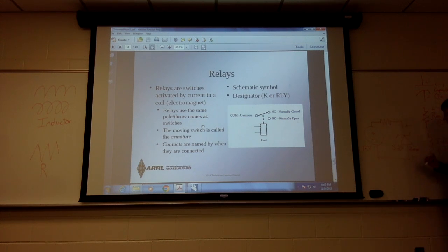What you can end up doing for over voltage protection is this: you won't have any current going through this resistor until this diode starts conducting over 5.2 volts. So if you add 4 volts here, there will be no current going through this resistor. You can use that to essentially turn on another transistor and crowbar the circuit.